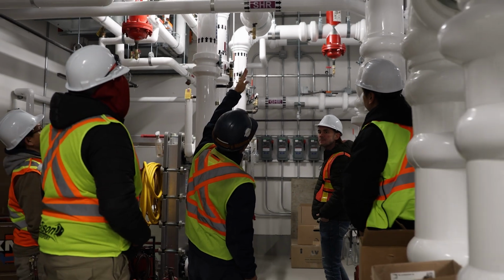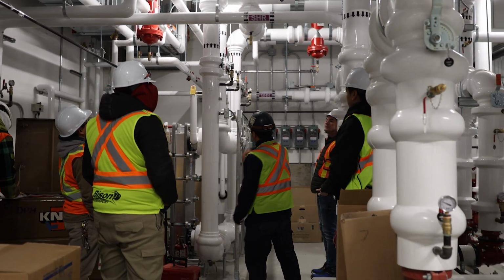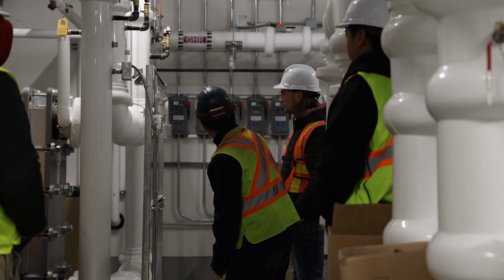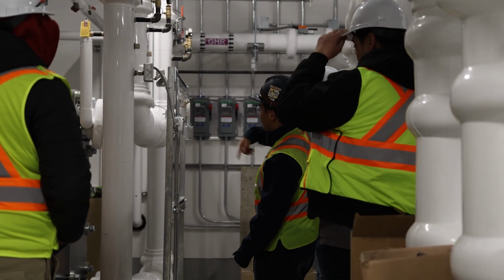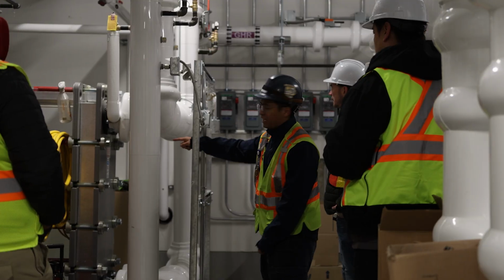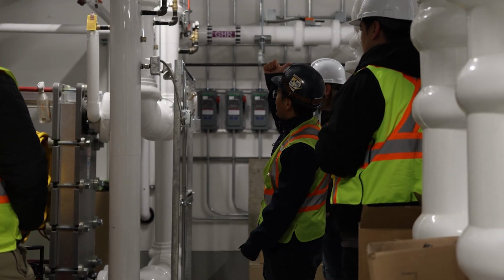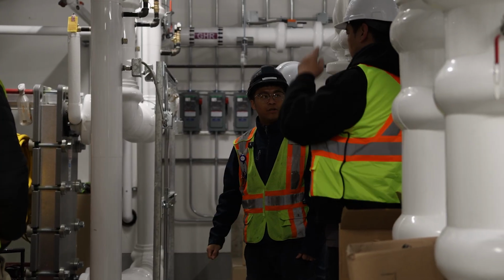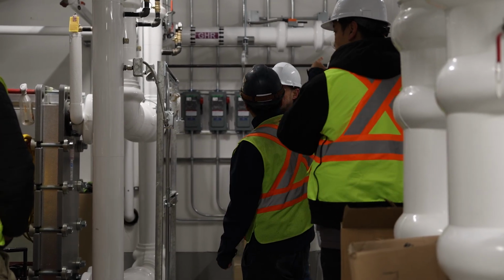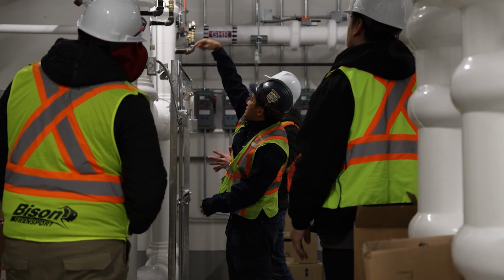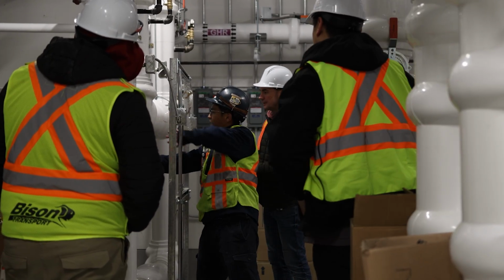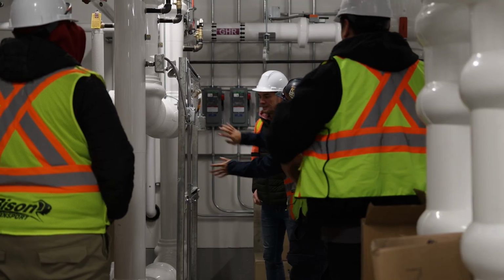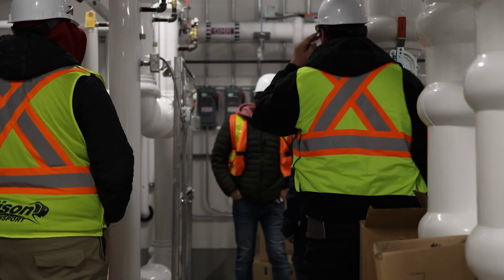So the three-way valve modulates to give more heat or less heat to heat exchanger 3. That pump does the flow recirculation, and the flow grabs the heat from heat exchanger 3 to maintain the heating HRV supply air temperature. So this does the heat for the HRV. This side goes up, the flow. This is one side, this is the other side. This side is only for the HRV, and this is the pump for the HRV.